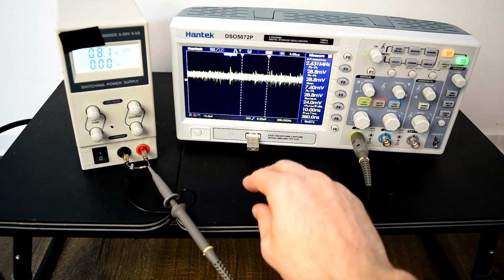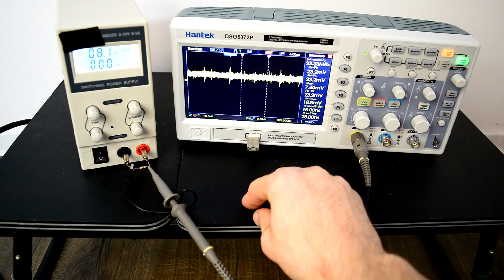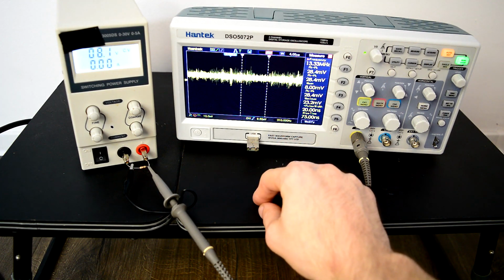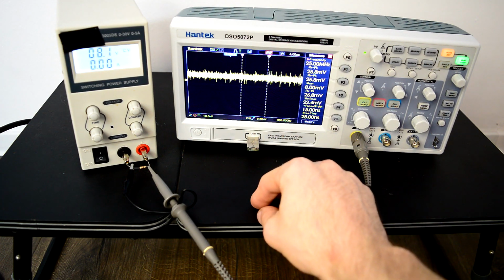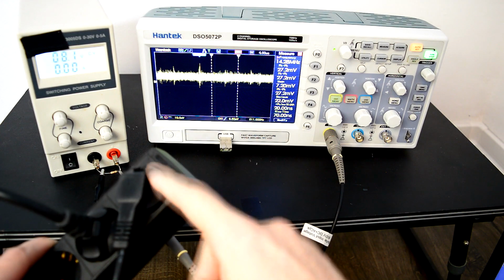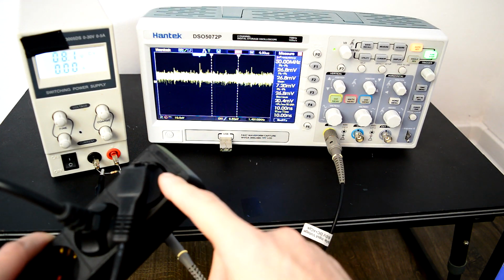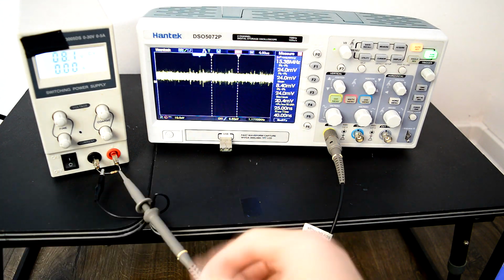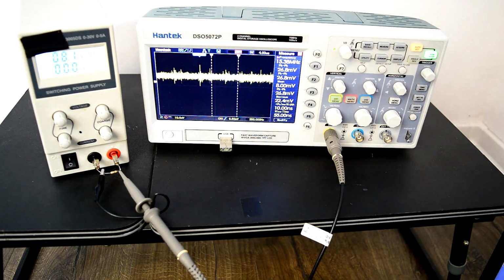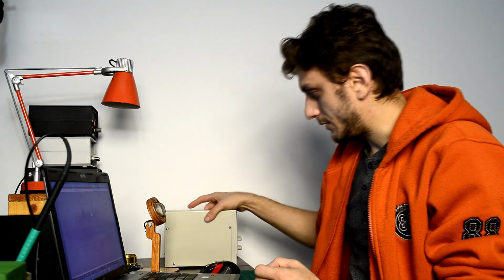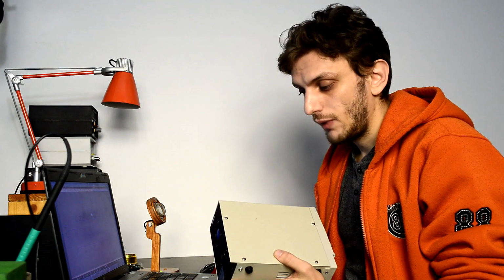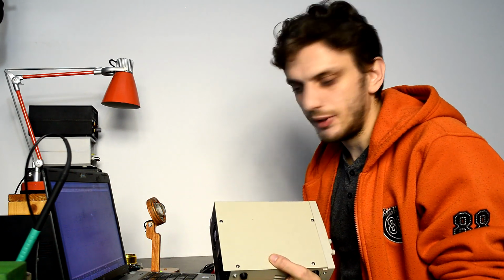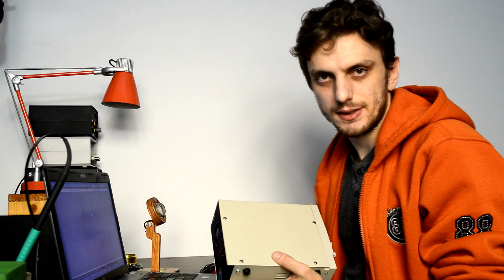And now we can start simulating using LTspice and try to find a way to reduce the noise that the supply is generating without isolating the earth ground, since that is not a solution. Let's see what we can do about this. Now, I won't be simulating the entire circuit because it would take forever to simulate, and because I don't have the actual schematic of the supply. I know it's a flyback type of supply, but I don't have the exact schematic.